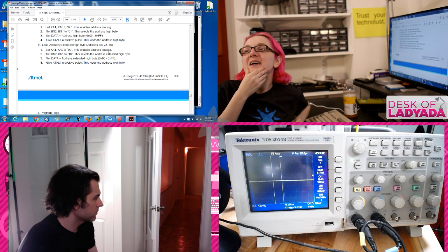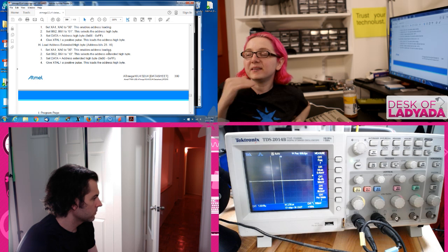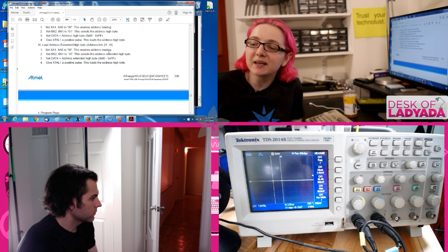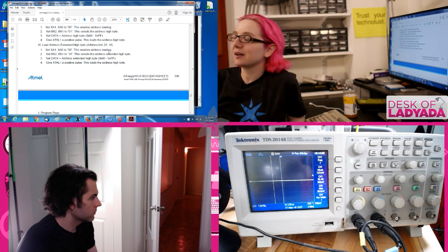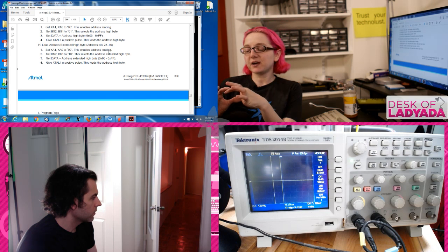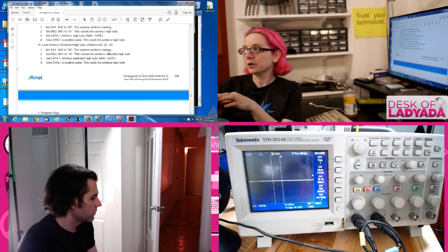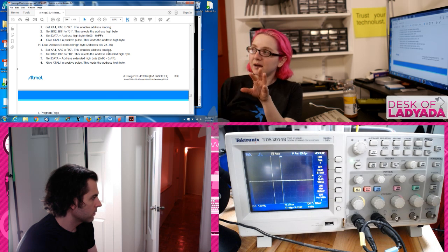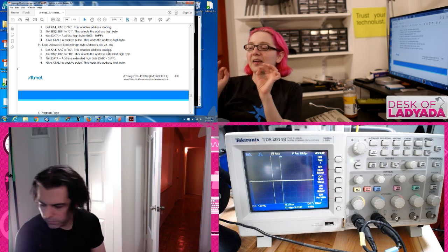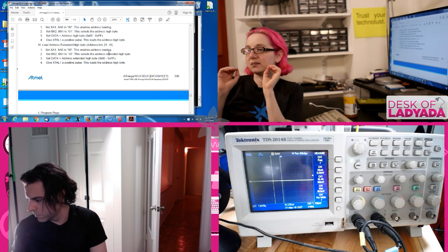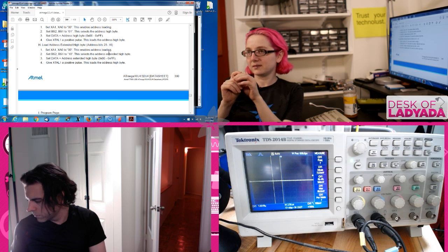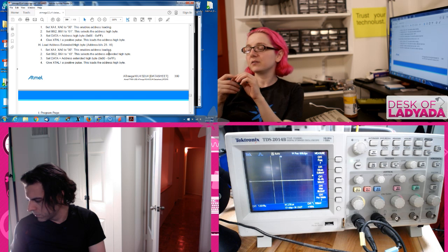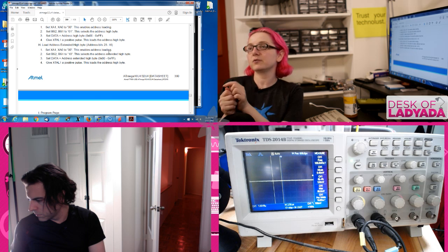I think that some of the basic SWD commands are. Okay, so it's a little bit like SPI Flash. This is another enjoyable thing. With SPI Flash there's the JEDEC standard. So reading one byte, writing one byte, and getting the chip ID is standard. Those three commands, everybody agrees on. Everyone agreed on this command to erase the byte. Every chip has this to read, this to write.